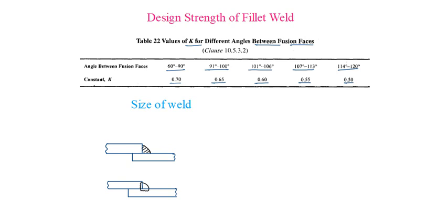So for theta less than 60 degrees and more than 120 degrees, fillet welds are not suitable. Are not preferred.